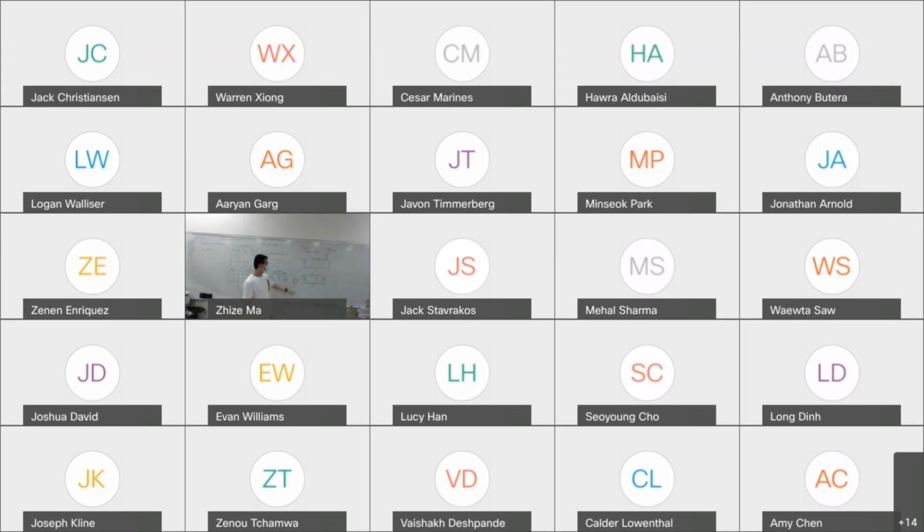Since you know these three light bulbs are in series, the same current goes through each of them, but you still want to measure the voltage for each of them. When you measure the current, you want to put your ammeter in series.